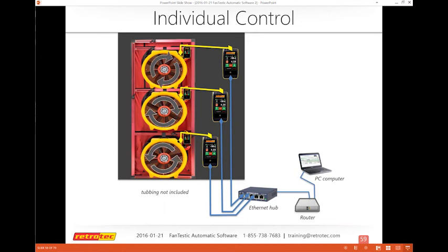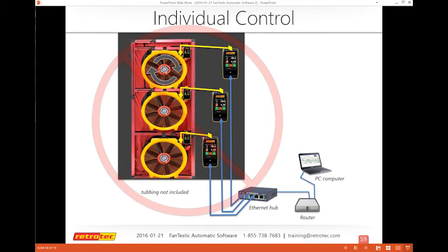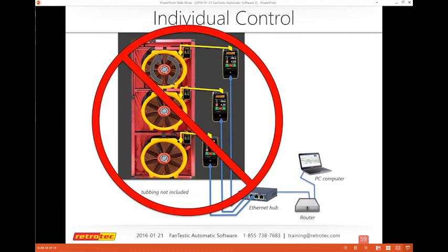Sometimes it's not apparent when you have these 3 fans stacked, but you may have 3 fans here, and you may have another hallway that's 10 feet away. Then the fans are actually in this common zone, and they're fighting each other. So that's why common control is a much better way to set these up so the fans are not fighting each other. And again, I can do this in the computer with my selections, or I can wire them in a way that allows them to do that. So this would not be the way to set that up.